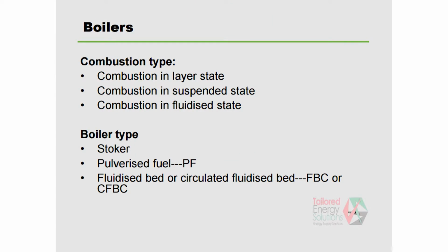Okay, let's quickly cover some boilers available in the country. That is the boiler classification by combustion. We have combustion on a grate, combustion in a suspended way, and in a fluidized way. On the grate, basically it's a stoker type of boiler. In suspended state, it's the pulverized fuel boiler, as in coal-fired power stations. The fluidized bed is associated with the fluidized state, FBC or CFBC.